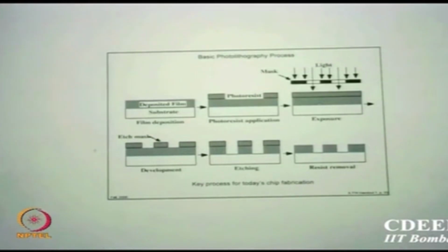The basic idea in making an integrated circuit or a device is to allow selective area processing. That means in certain regions I want to do a processing, and the rest should get masked. So the word itself suggests something has to be masked. The process allows that particular area which you want to protect from the next process to go through